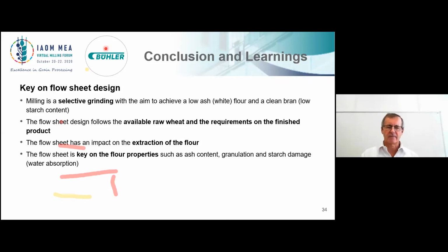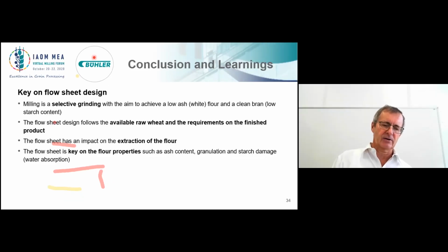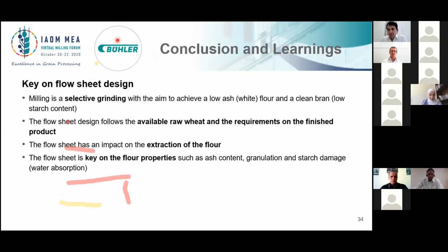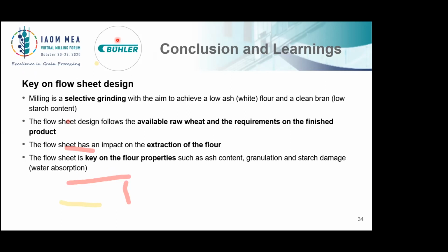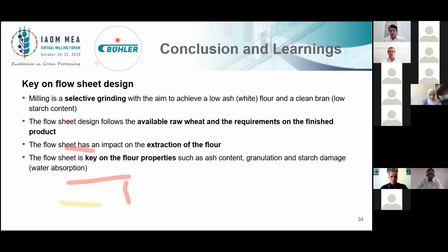Middlings does not help, and middlings is also creating an issue if you change wheat grist, because on a semi-hard or softer wheat you have much more middlings than on a hard wheat, and if you would use a purifier for those, you have a big issue and a real challenge on balancing the mill. So let's say three granulations should be purified, and you have a very consistent flow.